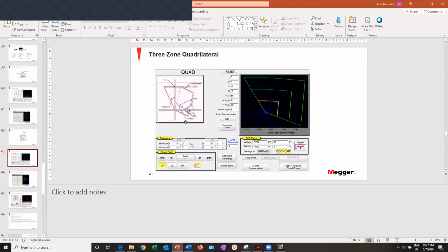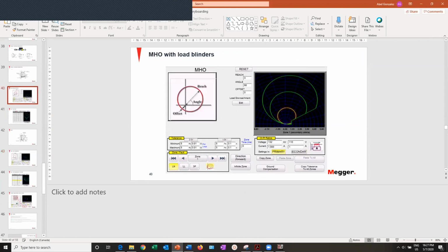A rule of thumb is you can differentiate a load from a fault with the power factor. Usually loads have a high power factor value, which would lead to a low X/R ratio. On the other hand, faults are more or less reactive in nature, and the X/R is quite high. So this is how the relay manufacturers also differentiate. I hope I answered the question.